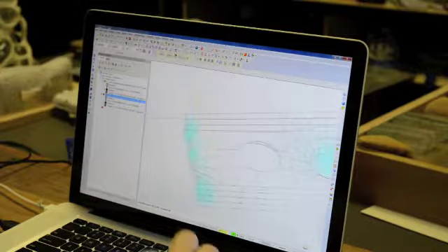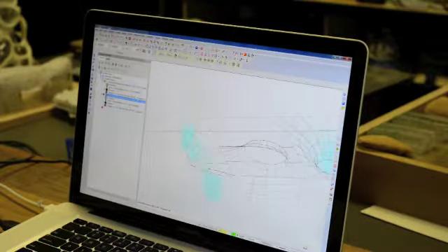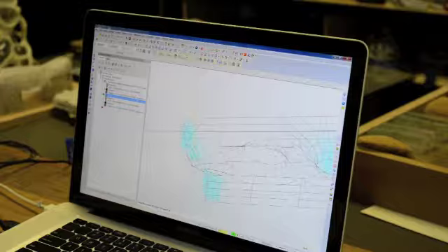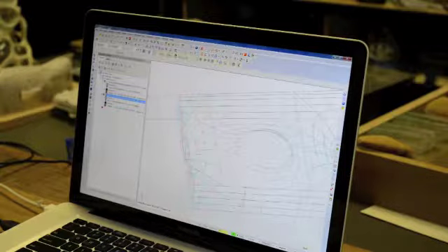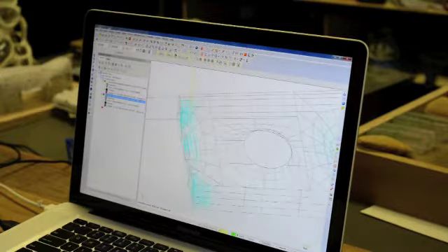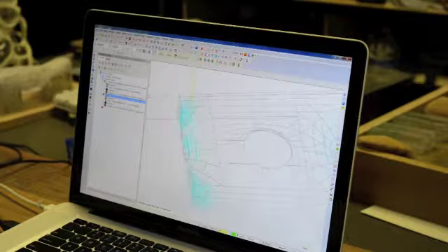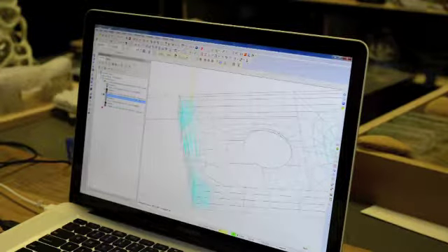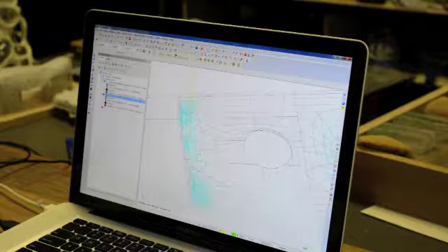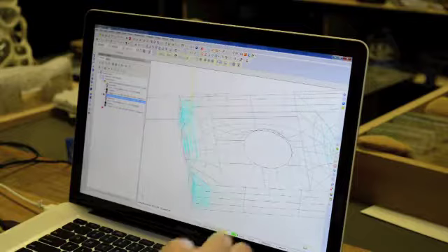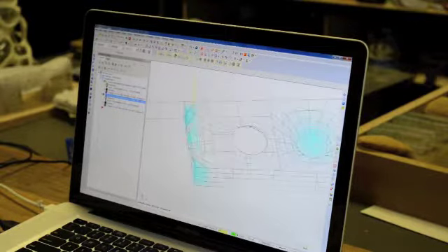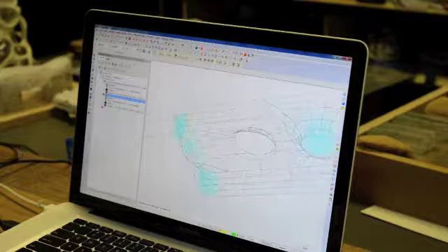And if you noticed, when I selected the containment, I just used the curves at the top here, so that could cause a problem, but we'll just have to preview it and see what it did, because sometimes you can be very economical with containment in that it doesn't necessarily have to follow the complex curvature of whatever your geometry is. Sometimes just a simple rectangle around it is enough. So containment's one of those things you always have to sort of experiment with.